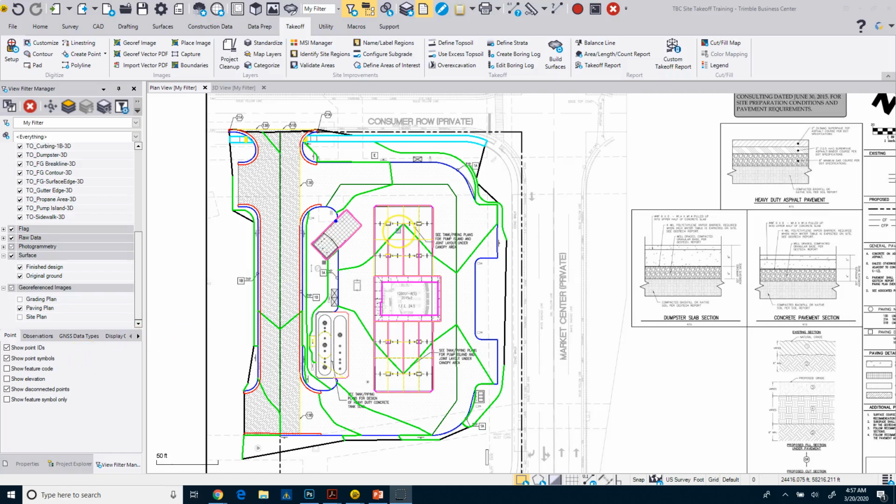All right, so now what we're going to do is basically define our potential boundary. When we put in our site improvement, we tell it that this area all in through here is this concrete pavement section, this over here is our asphalt pavement, and this over here is our dumpster slab. We can set up our materials and our thicknesses for each one of these sections, okay, and even our sod and our sidewalk, we can also define that.